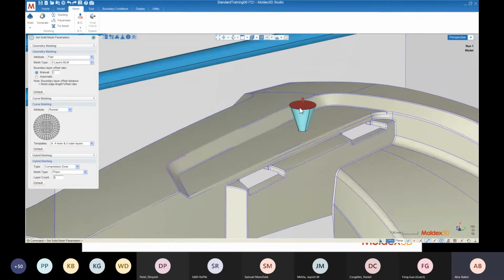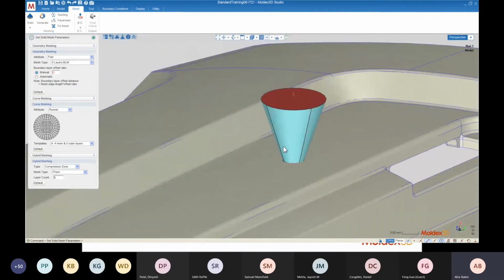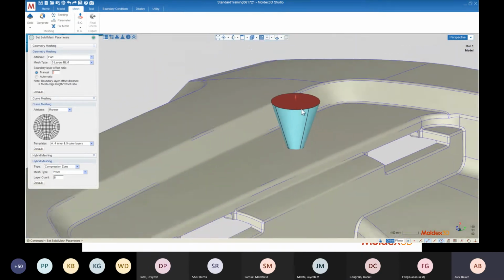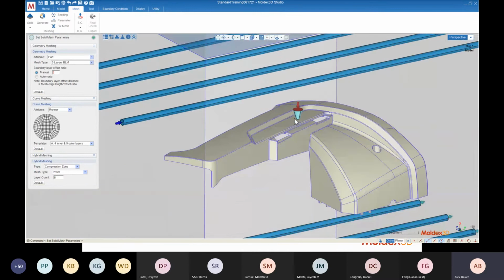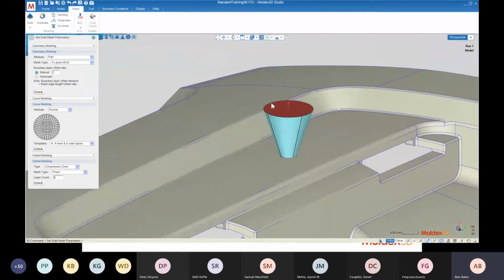The reason that I recommend line-defined elements over CAD geometries is specifically because of how we handle the solid mesh for line-defined objects. What we're going to do is we're going to define a two-dimensional template, which is going to be pasted onto the inlet. And then that template is going to be extruded along the line.